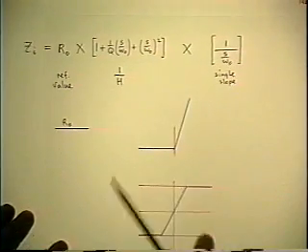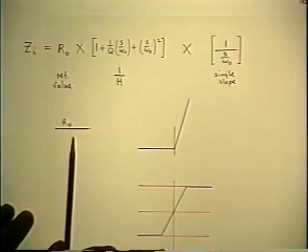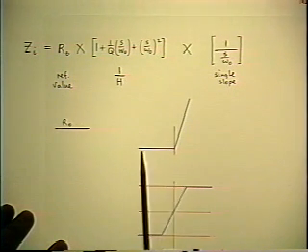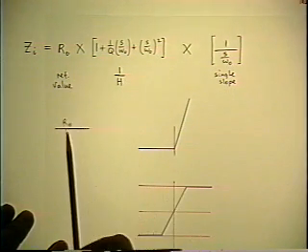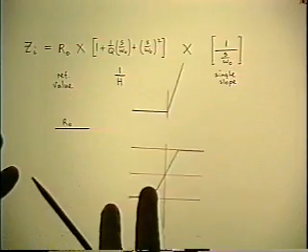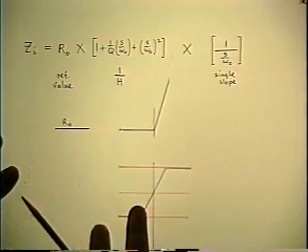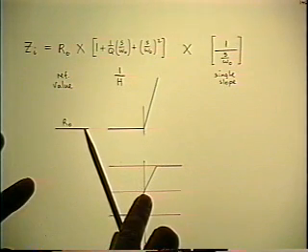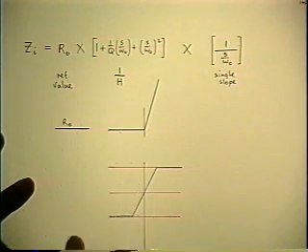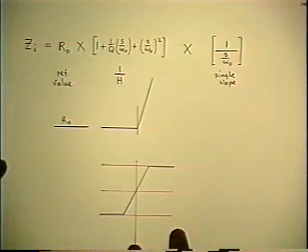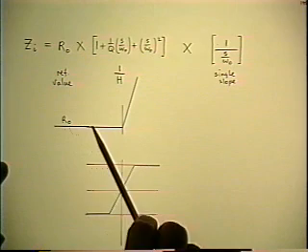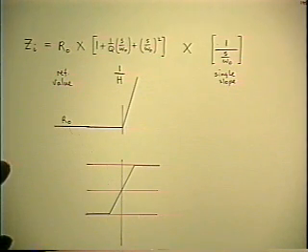Now I have to match this relative to the original reference. So 1 over H starts at 0 dB, which is unity, and then I scale that to the R0, so I have to make the vertical position line up with the R0. And the R0 doesn't have any frequency significance horizontally, so it doesn't matter where I put that, so I'll just join it on horizontally with the same line.